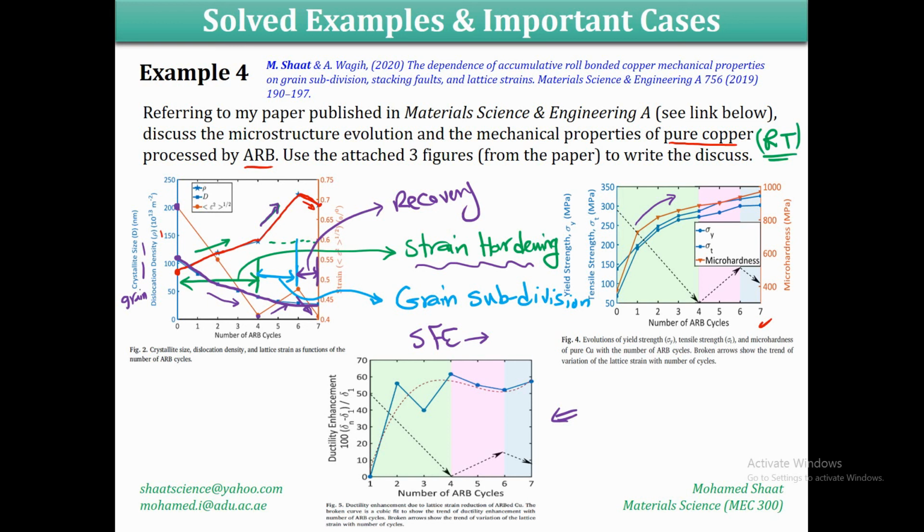grain boundaries within cycles 5 and 6, and that's why within the third range, as you can see, I'm splitting this figure into 3 regions. Within the middle region, we're gonna end up with an increase in the dislocation, an increase in the number of the high angle grain boundaries, and this is what increases the strength. It is gonna keep on increasing the strength of the material.